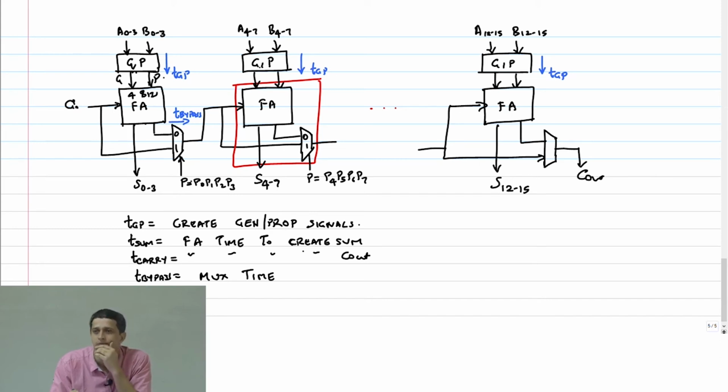Suppose it is. Right? Then, of course, from G5 to bit 7, it has to propagate. Right? After that, it's going to be in bypass mode. My worst case. Basically, if A15 and B15, that full adder happen to be in generate mode, then my carry is ready immediately.